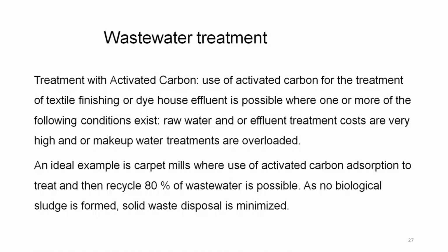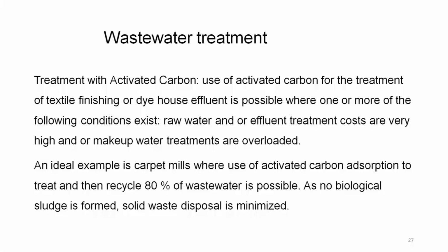Treatment with activated carbon for textile finishing or dye house effluent is possible where one or more of the following conditions exist. Raw water and/or effluent treatment costs are very high, and/or makeup water treatments are overloaded. So, if you have either of these two conditions, whether the raw water is very high in contaminants, or the water treatment system is overloaded, then simply by adding activated charcoal one can achieve treatment.